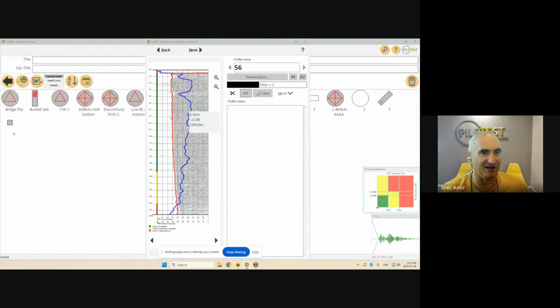So if you apply engineering judgment, you look at the cages on site, and you can see that the contractor is not doing a very good job in attaching the tubes to the cage, then you can definitely write that in a report, and you can save a lot of money for the contractor and a lot of trouble and time by just applying judgment and saying, guys, this is not a flaw, this is not a defect, it's just a false positive. The criteria is missing here because the criteria cannot think about non-parallel tubes.